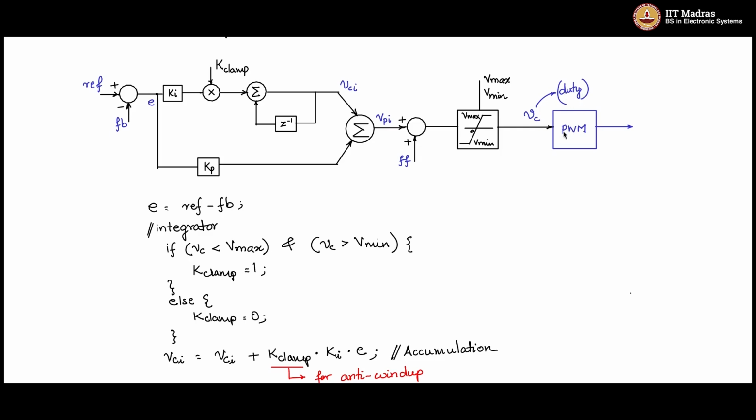And if you use the timer 0 counter of the ATtiny, you can compare with the timer 0 counter, and the output will be pulse width modulated wave shape like this, where you could have one edge getting modulated based on the value of VC. So this is the pulse width modulation signal.